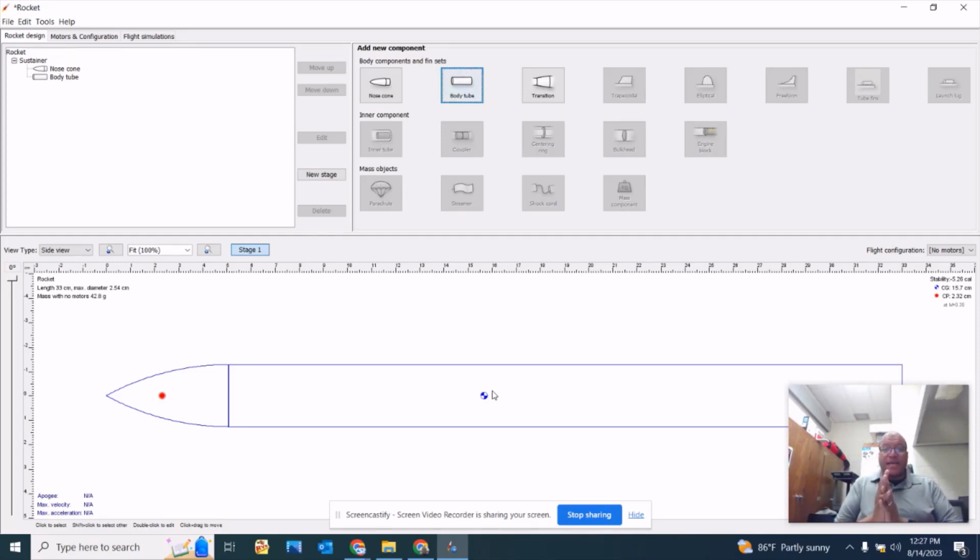And the reason being is, if your center of gravity is near the leading edge of your main wing, then the majority of the airflow is going to be going around your fins, and it's your fins that allow your rocket to stay stable and to launch straight up. Because you don't want your rocket to launch either to the left or to the right, because if it does, then it's taking away from potential height. Okay, so make sure that you try to align that center of gravity near the leading edge of your main wings.